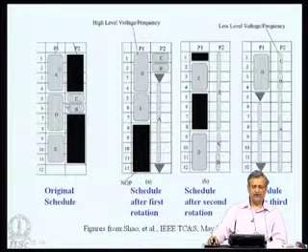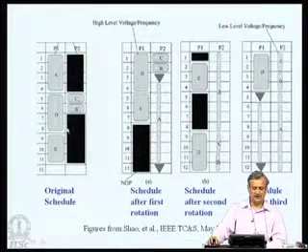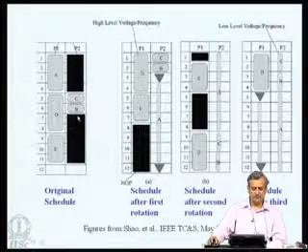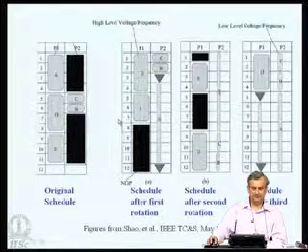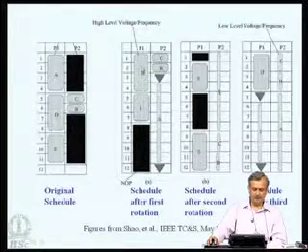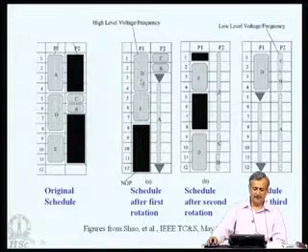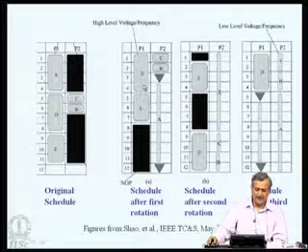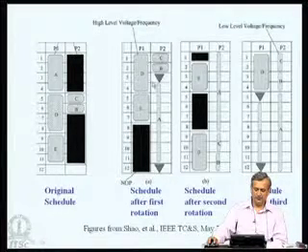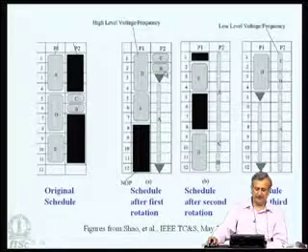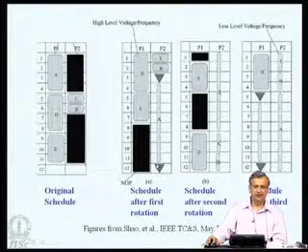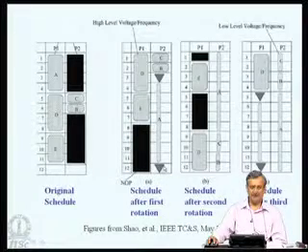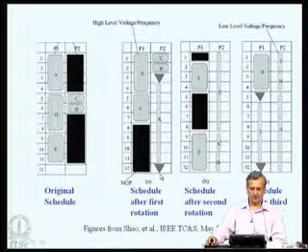Suppose we rotate the loop once. The question is, is it possible to actually do some dynamic voltage scaling and get some benefit out of it? Now processor 1 executes D and E, and A is scheduled on processor 2. Processor 2 executes C and B, and then it reduces the voltage, that is why there is a leaner bar here, executes A in a lean mode, that is a lower frequency mode, and then again changes the voltage back to normal.